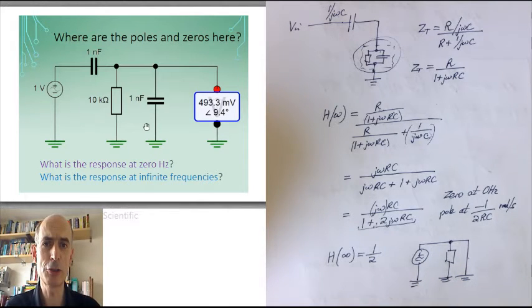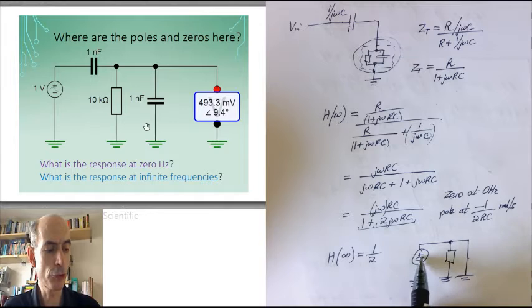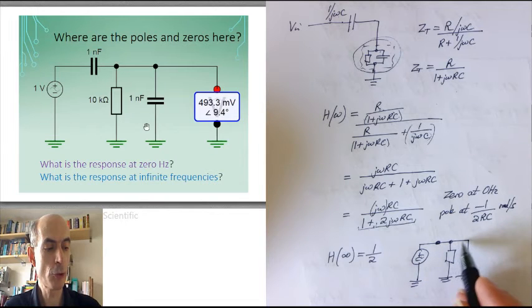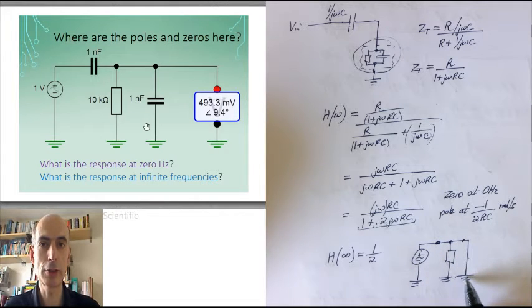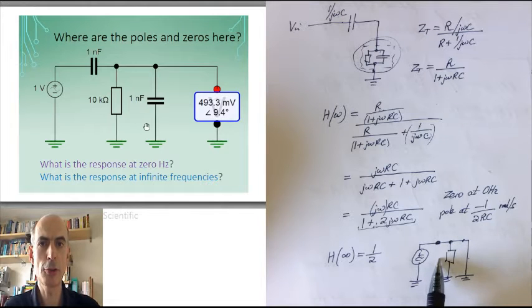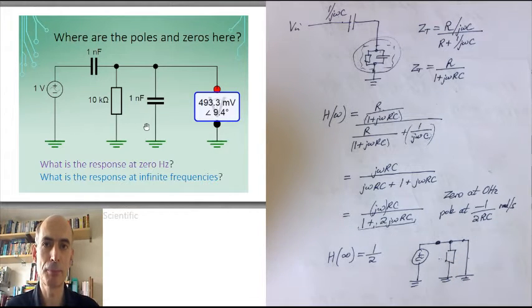And we've got a contradiction. The voltage source is forcing this node here to be an oscillation with an amplitude of 1 volt. But this node here is also tied directly to ground, so it must be at ground all the time. This circuit cannot exist.